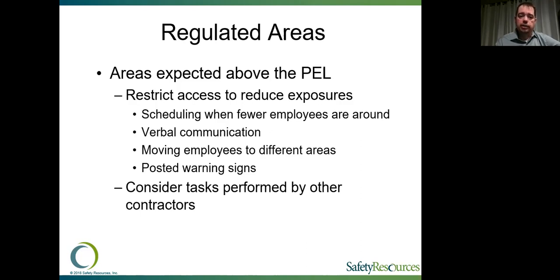We also need to keep in mind, and this is where a lot of contractors that may not typically have exposure to silica dust, they also need to identify when they are in spaces where another contractor may be creating an exposure that their employees are exposed to. So tasks that may not be performed by a particular group of contractors, either with one company or with a separate company, they need to be able to identify, hey, that dust is drifting over to this work area. Their control methods aren't being implemented properly. We need to stop and assess, and maybe talk to them and see about, hey, what control methods are in place, because I can't continue to perform my work here when you're pushing dust all the way over into my space.